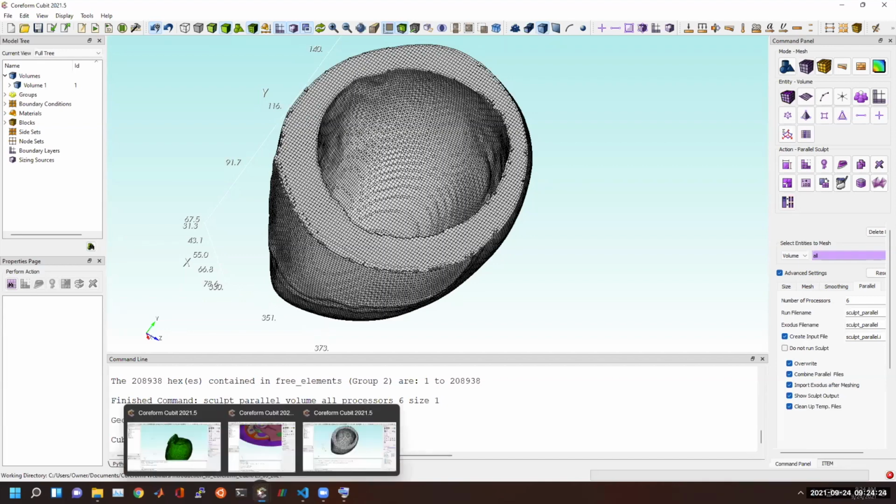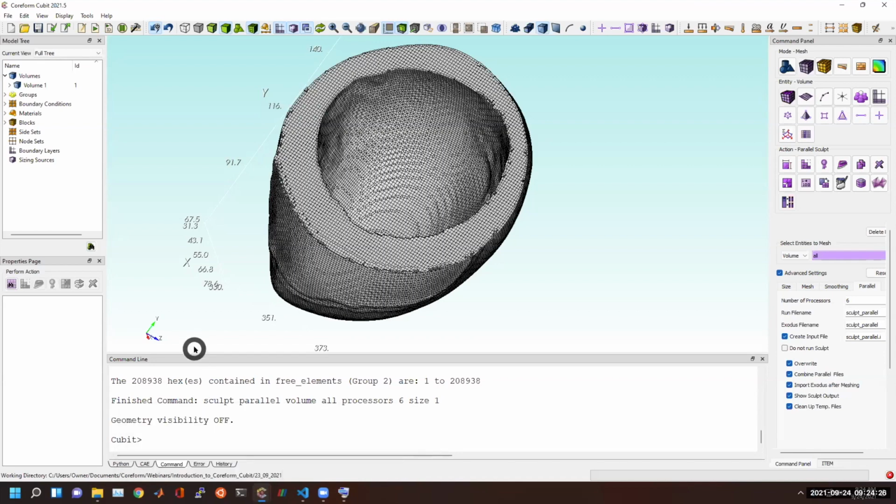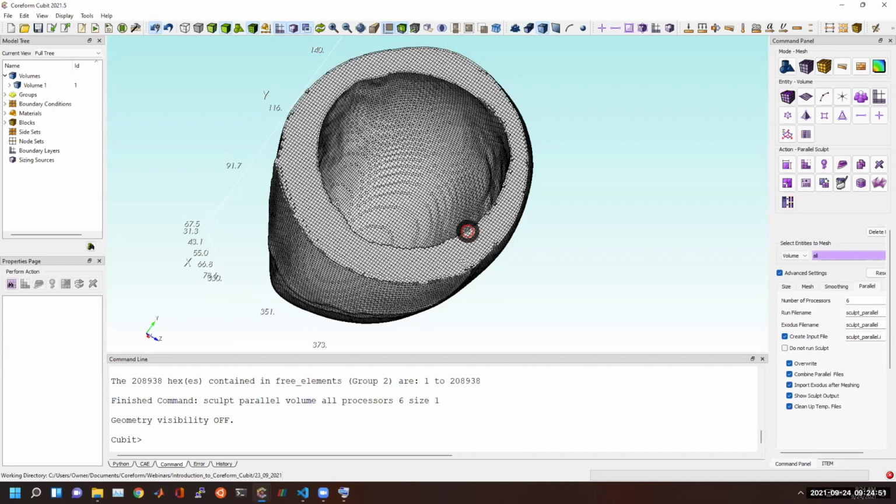While we can do some operations building hexahedral elements on, say, a well-defined CAD part that just happens to have been in STL format, when you have organic models, really the only way to build a hex mesh is through either an overset type of method, like an immersing method, or via Sculpt.